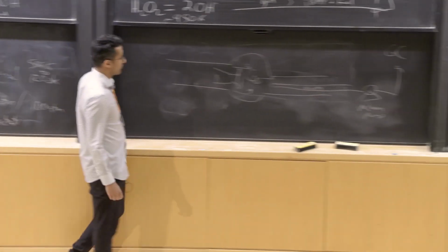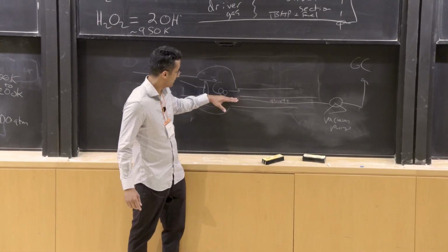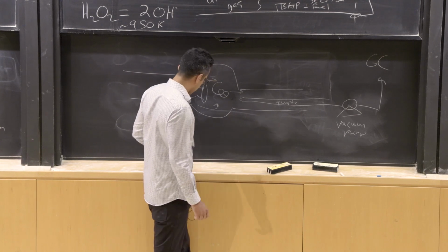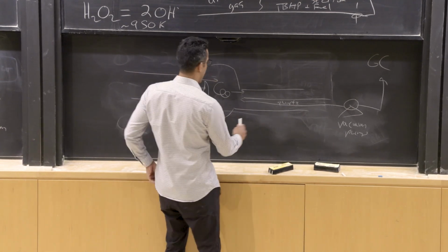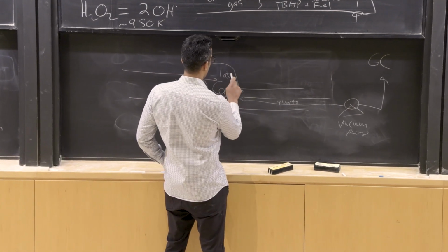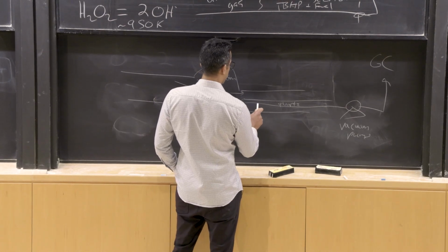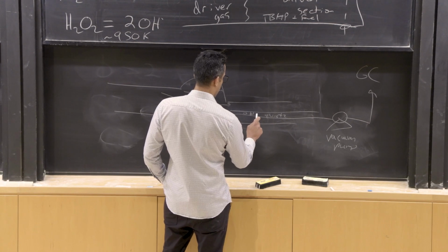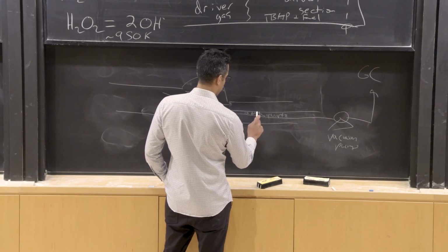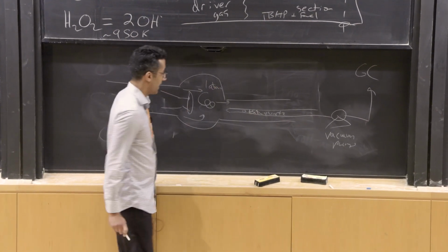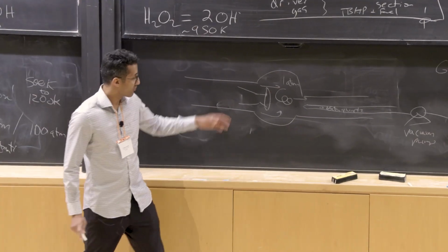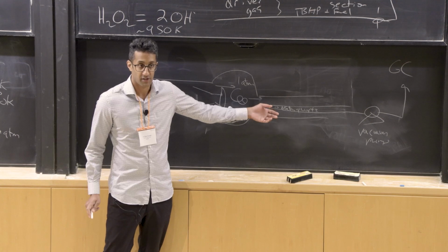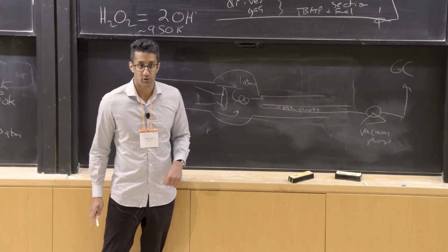So what you do is you don't really sample all the gas that's coming out. They sample it into a probe. This probe is connected to a vacuum, so the pressure here might be 1 bar. The pressure here might be 0.1 or 0.05 atmospheres, okay? And what that does is, if you have a rapid pressure drop as the gas enters here, of course there's a gas expansion that cools the gas. So that freezes a lot of the chemical reactions.